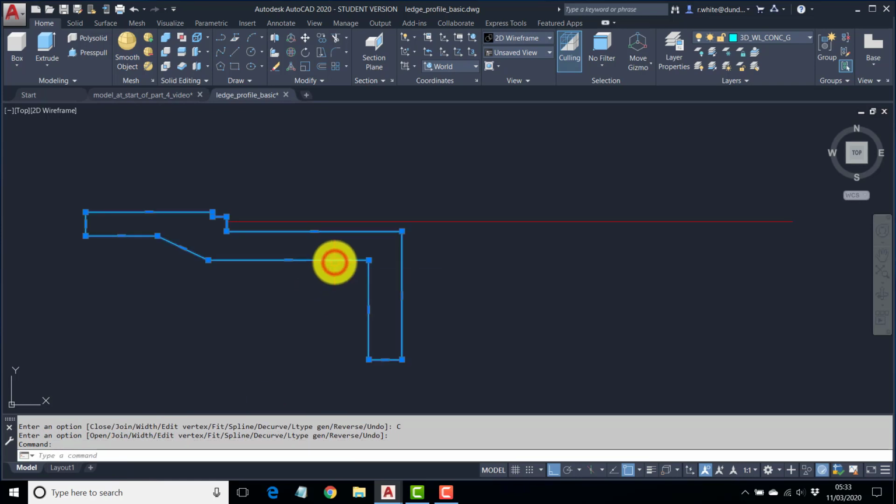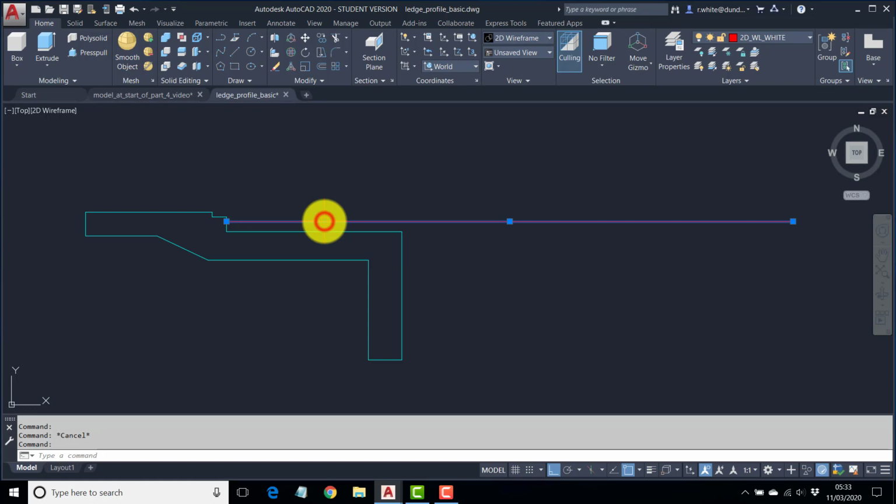So we should have the closed shape here, and the red line is actually the height of the gravel in the light well. Okay, so it's just slightly down from the window frames and the window area here, so that obviously any rainwater that fills in this area doesn't kind of come into the building. So there's a little bit of protection for the height there.